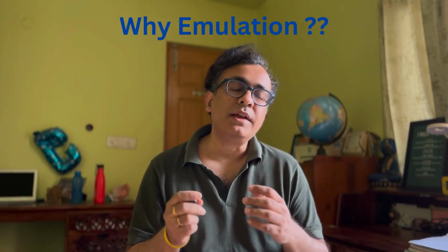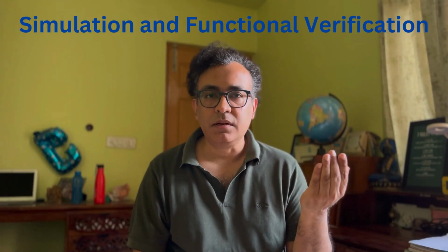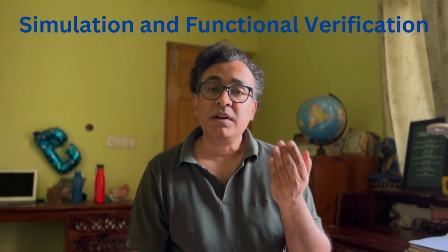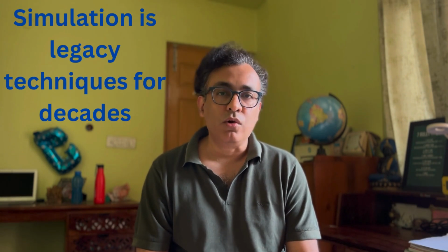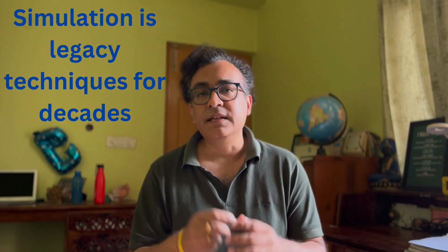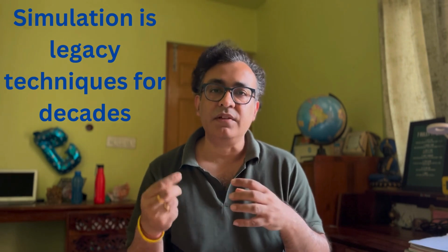We first talk about why emulation. We have simulation itself for doing functional verification, but still why do we need to know the emulation technique? Because simulation has been a technique for quite a long time, for decades. VLSI engineers check the verification output through the simulation technique itself. That means for a design you need to put in some random test vectors and judge the output of the circuit, by which you understand the functionality of the circuit itself.